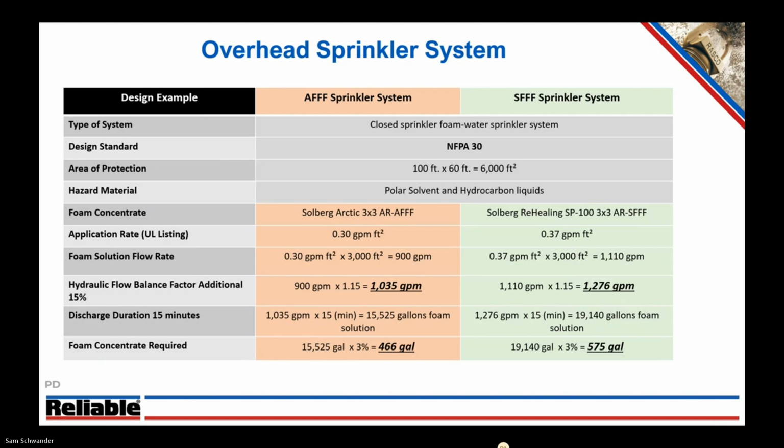There's a few implications that has on the system. Obviously a higher flow rate for the system. That's also going to increase the capacity needed for that 15-minute duration, so you're going to have a slightly larger tank. So when we're talking about system changeouts, it's not as simple. Again, there's not necessarily a drop-in replacement.